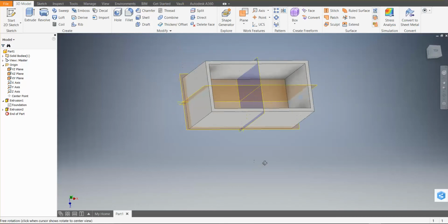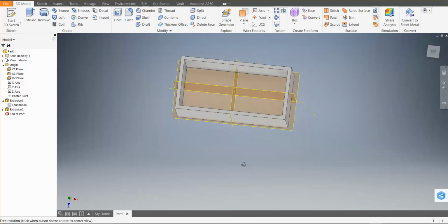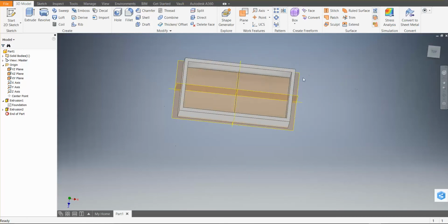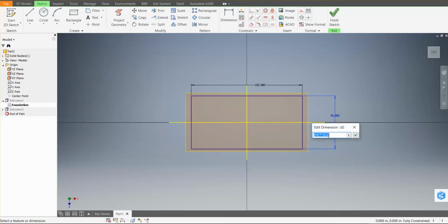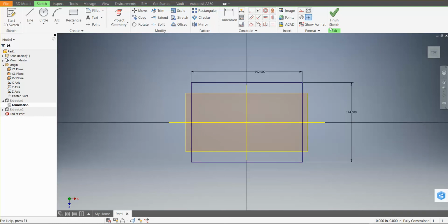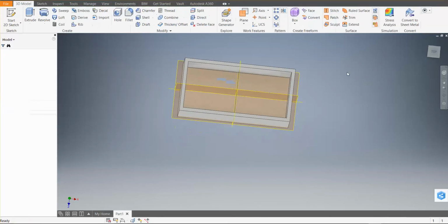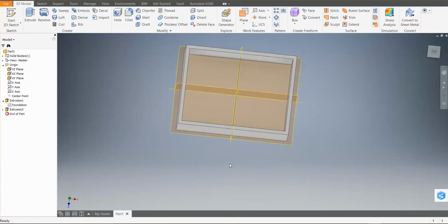And there's our vault right there. Once we do that, you'll notice if we go to the extrusion for the foundation here and change this to, let's say, 12 feet, it's going to update the sketch, and it'll automatically update that drawing. So now there's a relationship between these walls and that foundation.